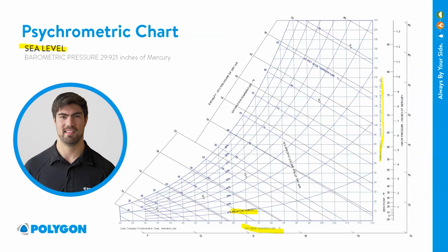So through psychrometric chart generating software, we're able to portray outside weather data that's been accumulated over 100 years through ASHRAE. We can portray that data here in the chart. So we can see the chart and the weather together so that we can see that worst case scenario and line it up with the inside target.